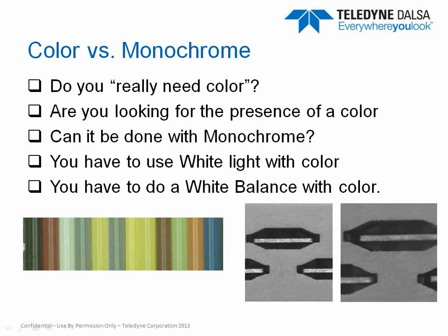In monochrome, again, there's also things you can do where you use a green light to enhance reds and so on. Depending on the color of LED lights that you use, it would enhance different colors. So again, you don't necessarily need a color camera when a lot of times a monochrome will do the application. So those are questions to ask yourself.